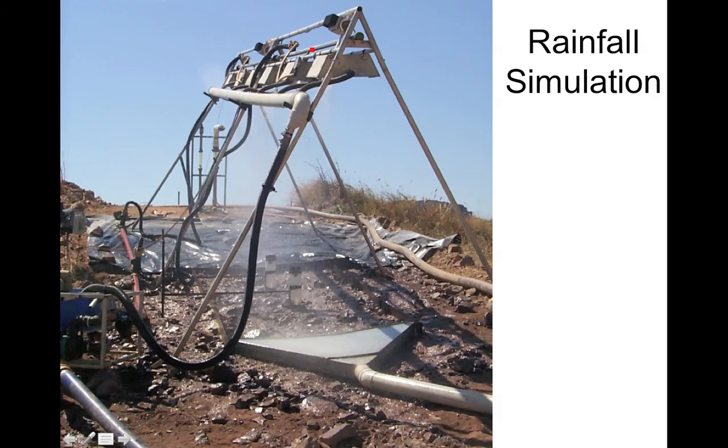So look, here's a rainfall simulator that's almost identical to the one that we had. It's a little bit longer. They've set up a bounds on the edge of this little plot so they know the area. They've got rain gauges in there. They've got their collector at the bottom here with some tubing coming off so they can measure the runoff from the erosion. There's their reservoir with the water going up the pump and so on. So they can do a whole bunch of experiments on these sites, looking at the effect of slope and rock armour and all sorts of things, right?